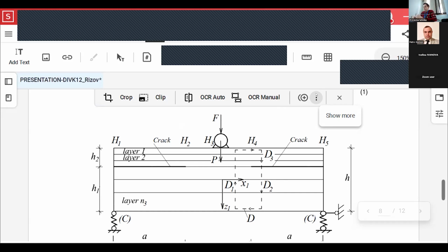The component explored is symmetrically delaminated by two delaminations at its two ends. Besides, the component is placed on two springs. The delamination under harmonic load is explored by the J integral. The extreme values of the total J are estimated.